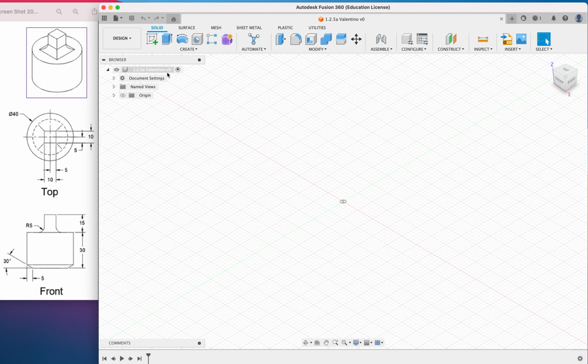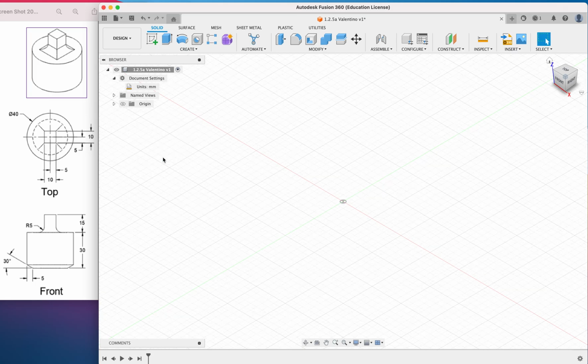Now, the first thing you need to know here is these are not in inches anymore. You can't see it here, but on the other thing you can see they're going to be in millimeters. So I go to Document Settings, Units, I click Change Active Units, and over here, I'm just going to drag it over here to be close. It is going to say what you want it in. I want it in millimeters. I'm not going to set it as default. I'm just going to change it for now. Double check to make sure it's there. Awesome, and now we're good.